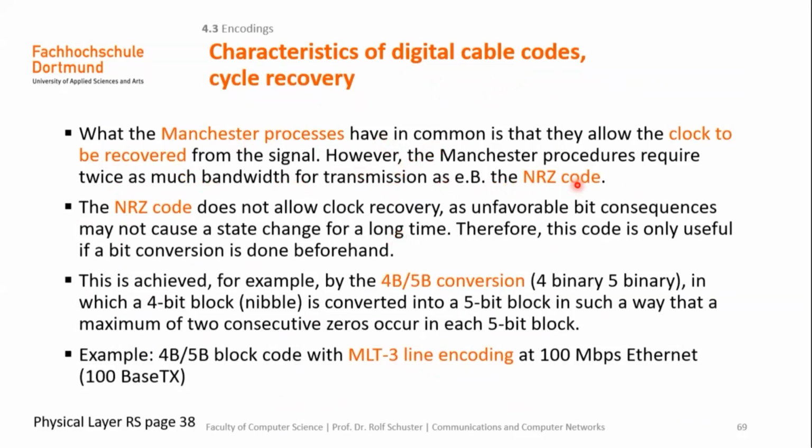That is what we could see in the explanation of NRZ and the explanation of Manchester coding. The NRZ code doesn't allow clock recovery, it's not self-clocking, as unfavorable bit sequences may not cause a state change for a long time. Therefore, this code is only useful if a bit conversion is done beforehand.